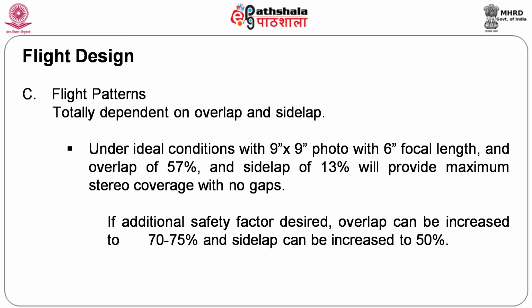Of course, if it is required, you can also go for an overlap of 70 to 75% and a side lap of 50%, but this will increase the number of photographs. So, if you decide, okay, this is what I am going to do, this is how I am going to work, I will have to decide what the side lap is, what the overlap is.